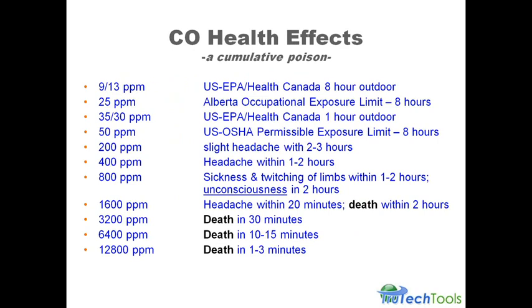There are industry standards, and the standard says if you're going to follow our standard, like the BPI standard, this is the maximum amount we're going to allow you to find in a home and permit you to do weatherization or permit the furnace to keep operating. But what you're talking about is what we call a reasonable standard of care. Let's say you end up in court somewhere. They're going to look at what the industry standards are. This person had 400 ppm of CO in their house, and there's no standard that would allow that. They can look at the building code standards, BPI standards, ASHRAE standards, ACCA standards, anybody that writes standards. They would say obviously this guy didn't follow a reasonable standard of care because the industry standards say what he's supposed to do.